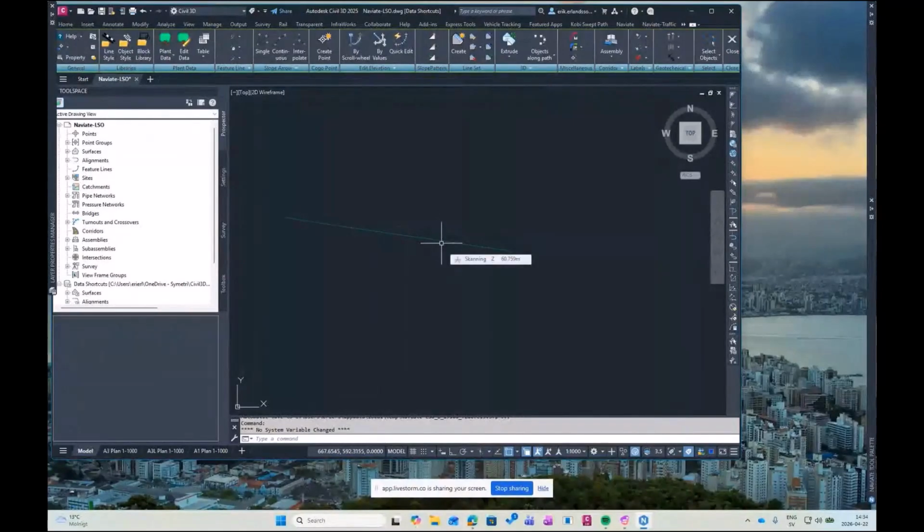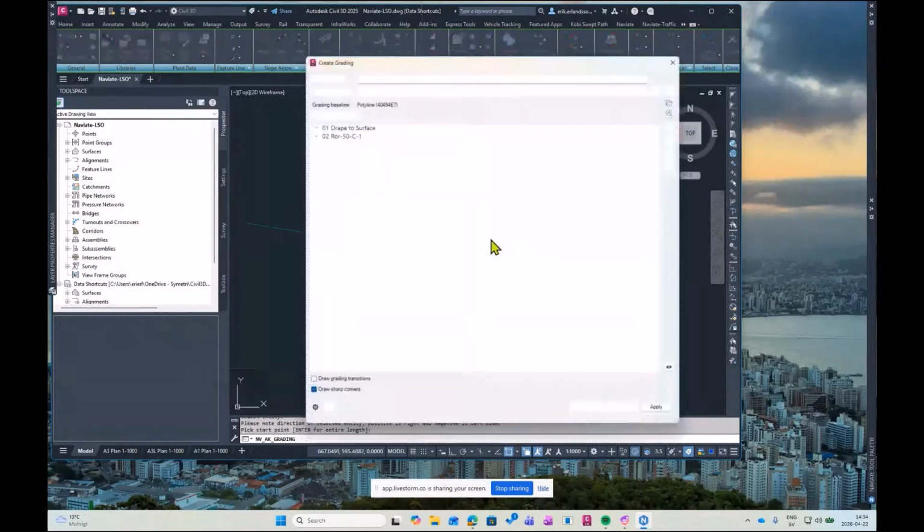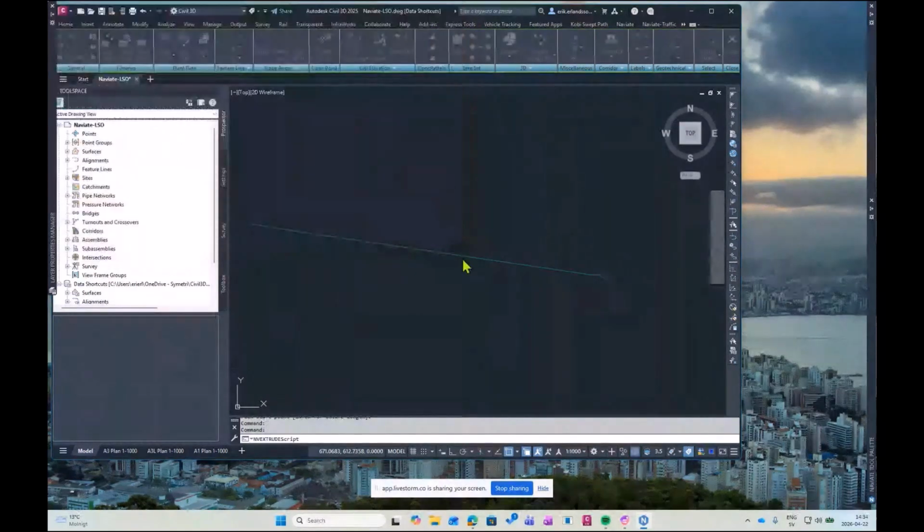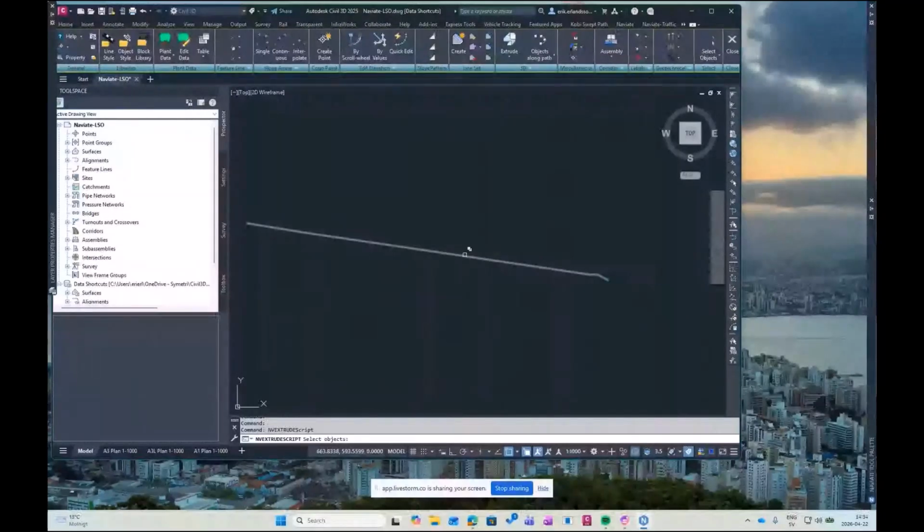So let's get some excavation going here. I would like to know how much I need to dig out to get this pipe in the ground. So I'll start with doing the same thing I've done in my other blocks here. So let's create the pipe, and we do extrude by script once again to get the pipe ready like this.